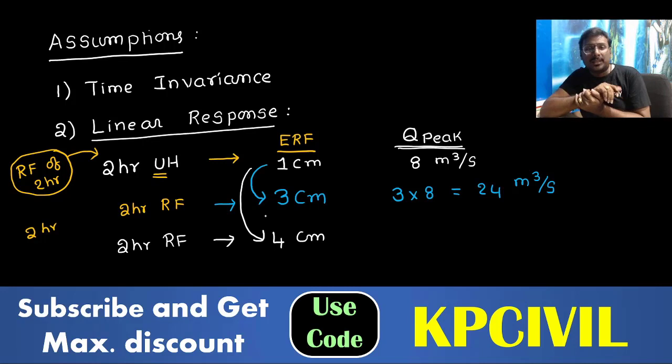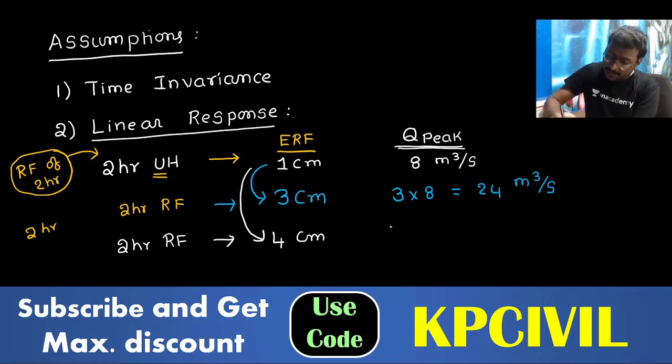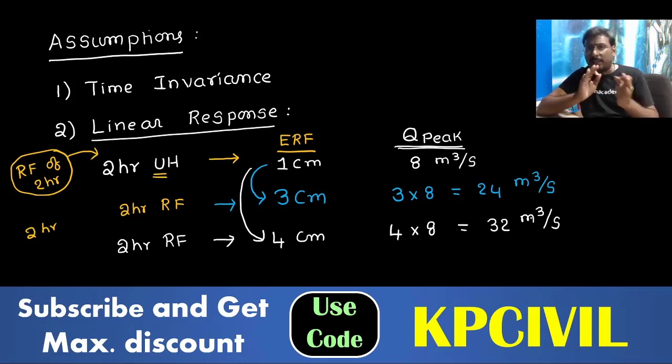Same catchment area, same duration, same slope, same shape, everything same, not modified. 1 centimeter resulted in 8 meter cube per second. All properties constant, only depth changes, so 4 centimeter results in 4 into 8, 32 meter cube per second.